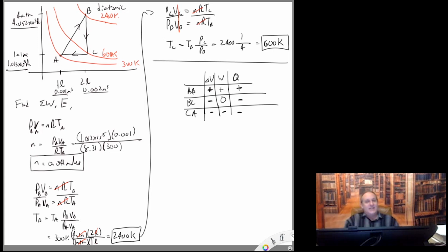It's not constant volume, it's not constant pressure, it's not one of those red isothermal lines, it's not that curvy adiabatic line. So we don't have a formula for Q for this process. So that means we have to sort of sneak in the back door to find Q. And there are two different methods we can use.